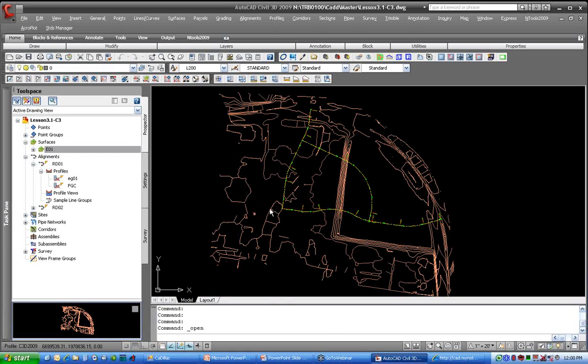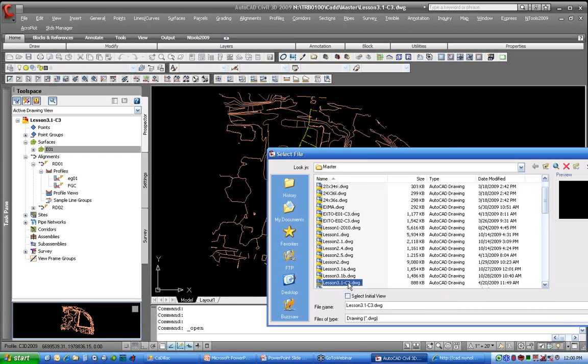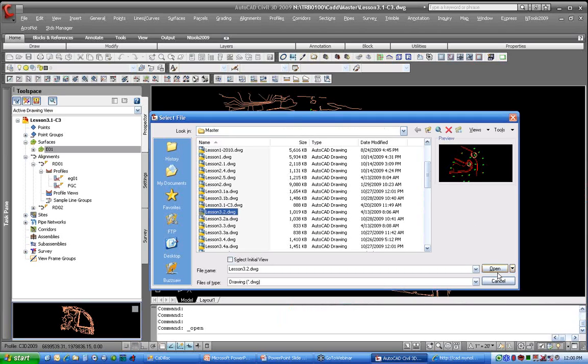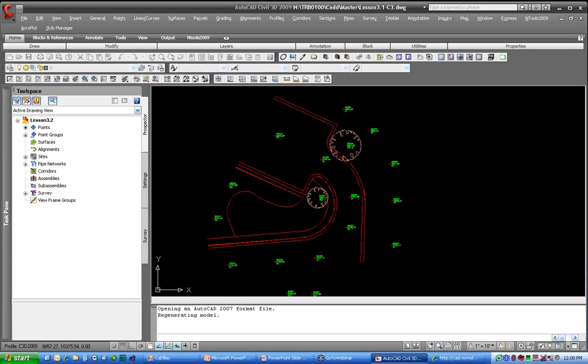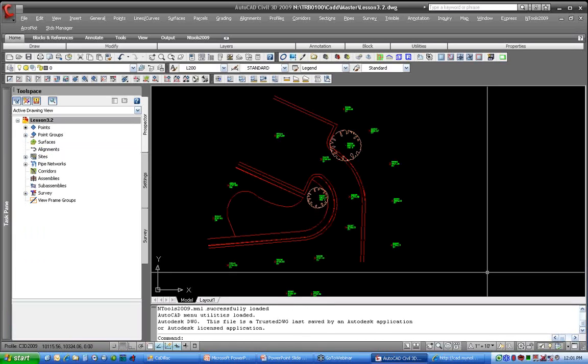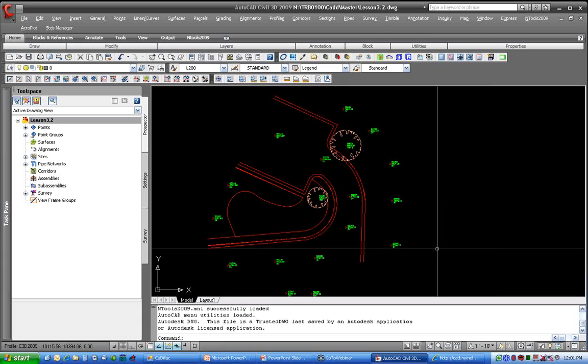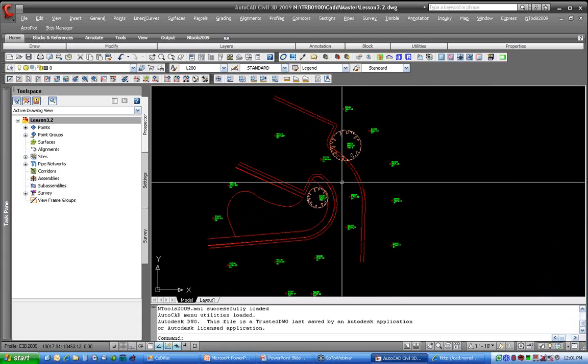And I'm going to open up a drawing here with some surface data in it. And we'll get my item on the screen here. So I've got a drawing with some points and feature lines. And these are actually brought in from a survey we did a couple years ago doing training on field coding in the Denver office. And what I've done is I stripped out that data set to be just the resulting feature lines or figures from their stringing, which are all the curved lines, and then also the spot elevation points in the drawing. So I've got COGO points, and I've got all these feature lines.